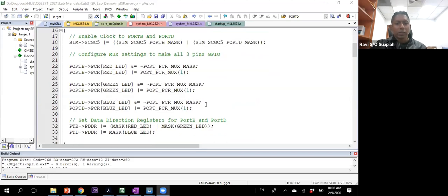Okay, so there's a sharing here by Neil. Don't heat up the contacts too much because it will melt the plastics. Yeah, so try to keep... I think you should never keep the soldering iron on the contact for too long.